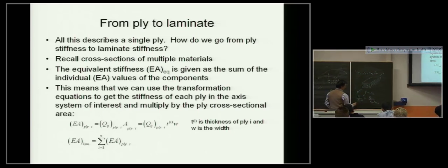So at the same time, I know that the summation of Fi equals F total. All the forces in all the layers have to, by force equivalence, add up to the total force. So on the one hand, I know that the ith force relates to the total force through this relationship, and on the other, I know that the summation of all the forces for each of the plies is equal to the total force.